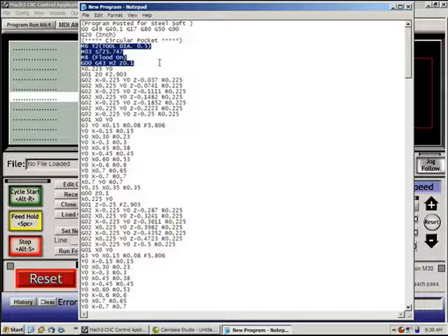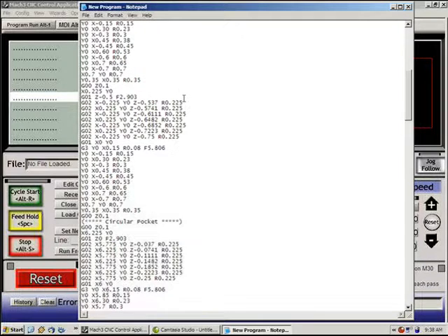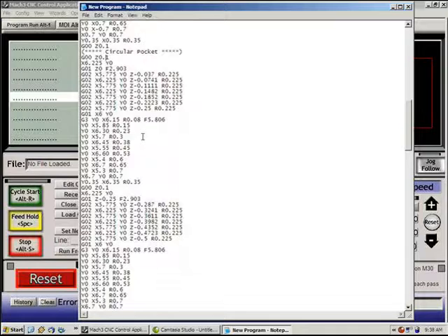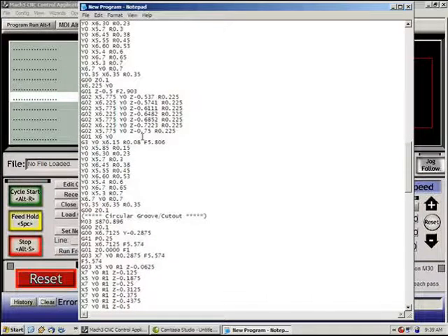This is put in every time you make a tool change, or you change the tool data inside the tool selection page. And if we scroll down, we'll see that we have our next circular pocket, but we don't have any tool data. This is because we didn't select any new tool data. Whereas if we go to the next section on our groove, where we were cleaning out the pass, we did change our spindle RPM, which is why we now have that.